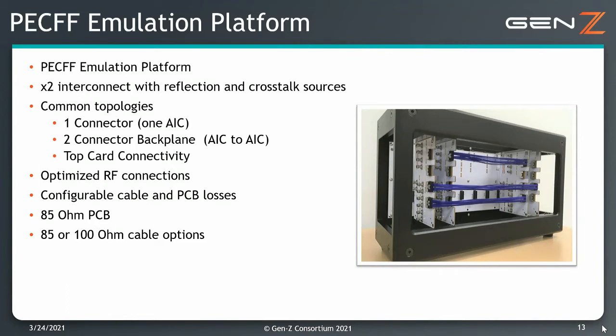The cables can be adjusted to any length, or manufactured to any length, to test whatever configuration a user may come up with. The PCBs support 85 ohm impedance, and the cables are flexible enough to support 85 or 100 ohm impedance.